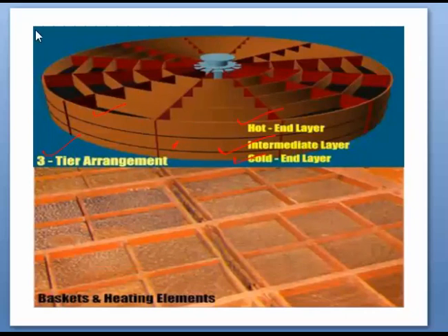As we discussed earlier, all these segments are filled with the heating elements, and they are like this. These are the in between heating elements which are filled here in these sectors. They absorb the heat of the flue gas in the first rotation, and when they come across the cold fluid, they release their heat.